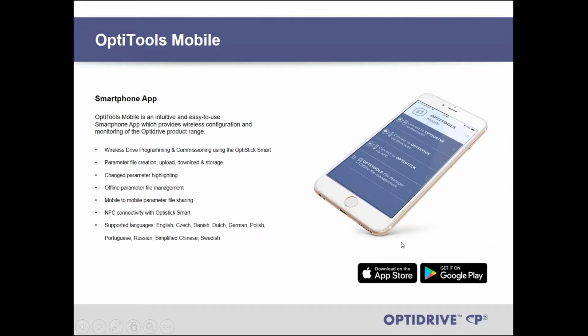Sometimes the control cabinet is far from my motor, or maybe the mechanism that I want to analyze, and I want to watch how it's working. And you can use your cell phone to start, to stop, to jog maybe the motors, and this can be really, really useful in commissioning.